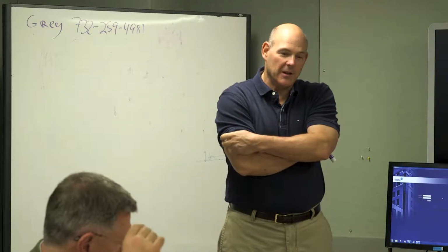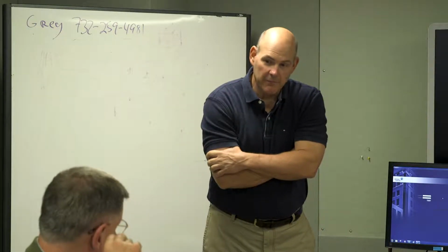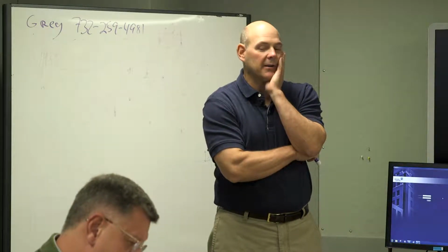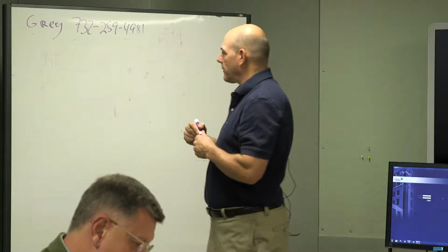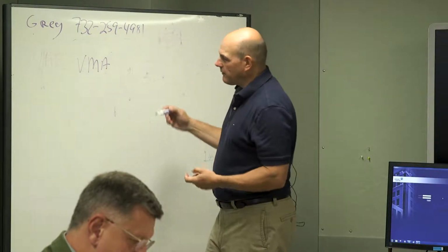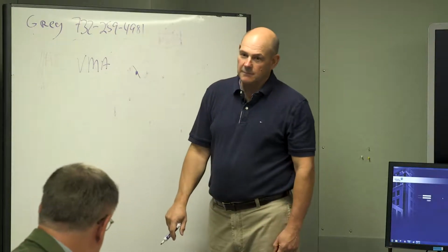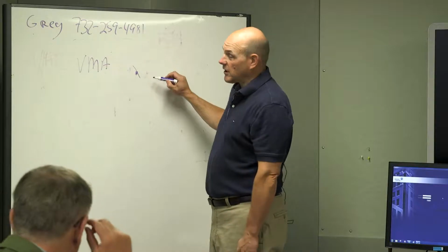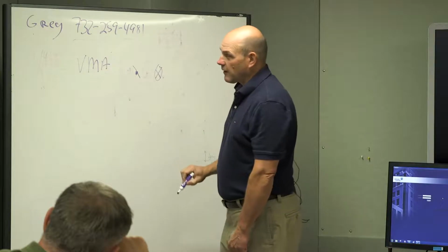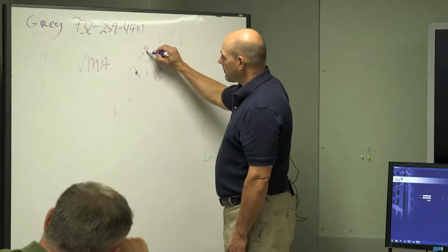So you guys good? Because then that box with VMA, right? I had mentioned that before. That's a controller inside the VAV box. I mean, we're not doing it for this, but I'll go over it now anyway. Basically, in a VAV box, there is a little shaft, right? And it controls a damper, right? And then the other device you have is a ring, a cross. That's an airflow station. So you have an airflow station, and you have your damper.